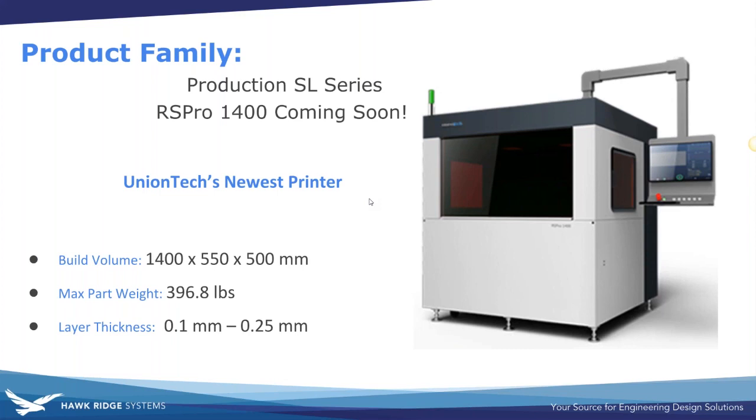Because if you mess up when you make an injection mold, it's going to cost you a lot of money, it's going to cost a lot of time, and you may miss deadlines. So that's where these printers really shine. And you have the same resolution and accuracy. You can see you can go down to 100 microns or 0.1. So you have really thin layers, really accurate because it's a laser, not many moving parts, just a scanning system and the build platform that goes up and down.